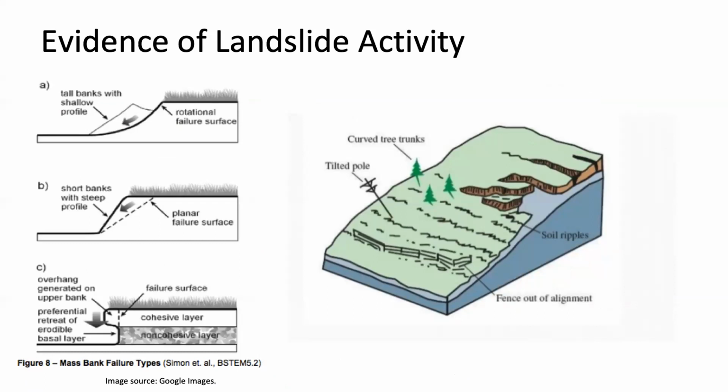Next on the list is a slide failure, also called a wedge failure. It's really just a wedge that either slides or plops right off of the slope. And then what we see on the bottom of that list is an overhanging slope failure, which is a result of toe erosion in an area that happens to be well vegetated with shallow rooted plants such as grasses or invasives that have really heavy roots for a really shallow distance.